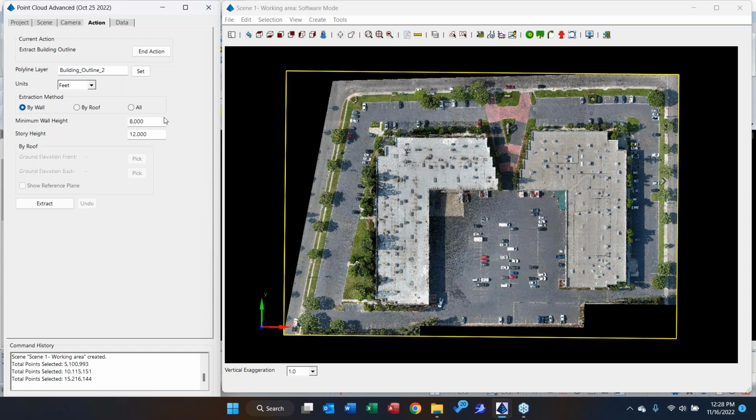Units, this is important, guys. Make a note. Point clouds tend to be unitless. Now, when it comes from a drone, like photogrammetry, photo capture, it's going to give you all the information of projections, like California. So this is California, not 83, California zone 5.